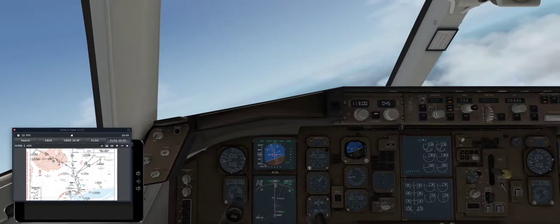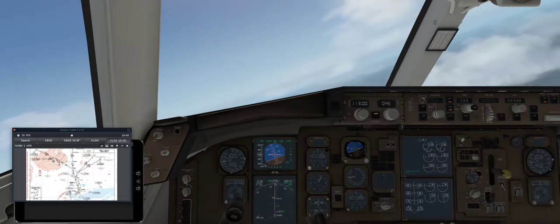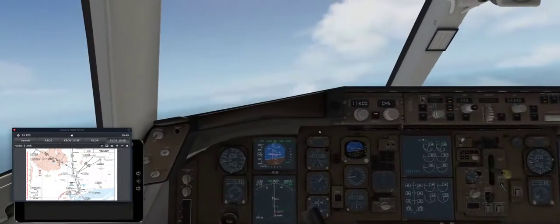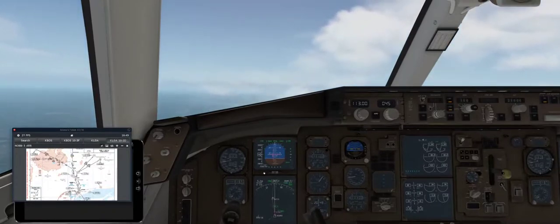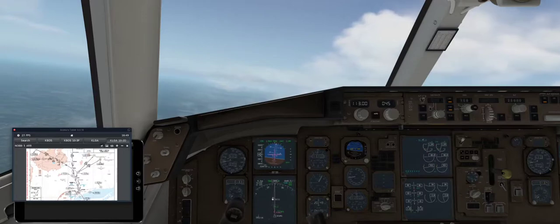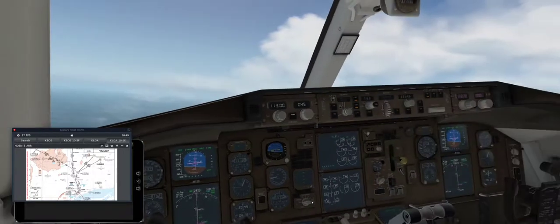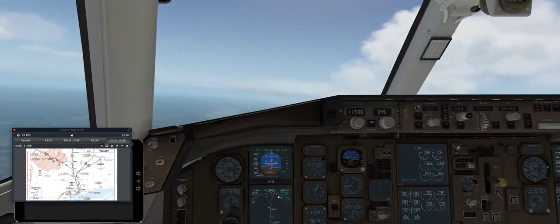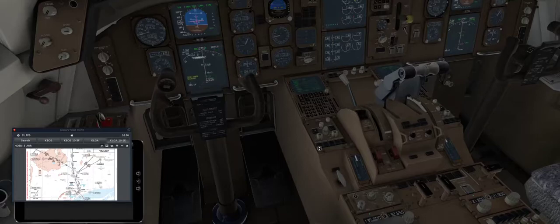It's probably time to go ahead and change to standard 2992. And we gotta do both sides. No, that's right, Pats, and then it's going to go to BAF, and we can see that by scrolling out further. Pats ends, then we go to BAF, and there's our top of descent. So like I said, we're not going to have a very long stretch where we're at cruise, and then this is that arrival and our descent.